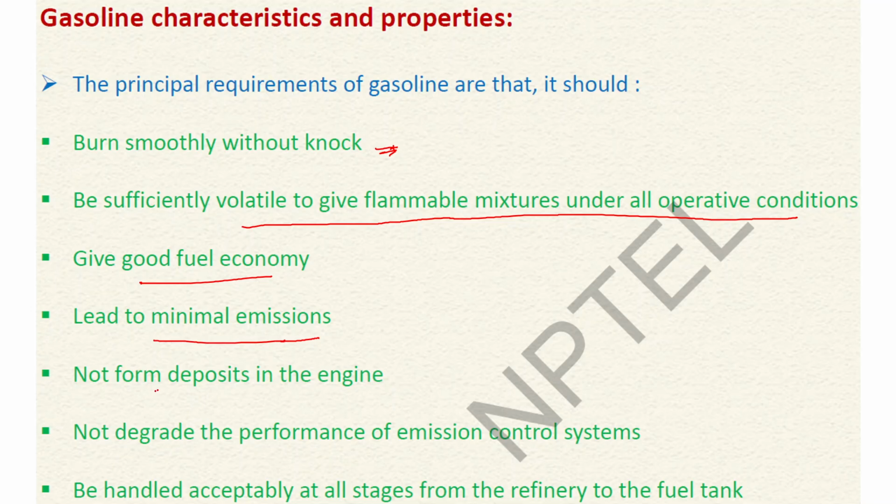It should not form deposits in the engine. As told earlier, the gasoline is stored in a floating head storage vessel, so coming in contact with atmospheric oxygen, it forms gums. These gums can clog the engine and can also lead to corrosion of the engine. So the presence of gum should not be there in the gasoline. It should not degrade the performance of the emission control system.